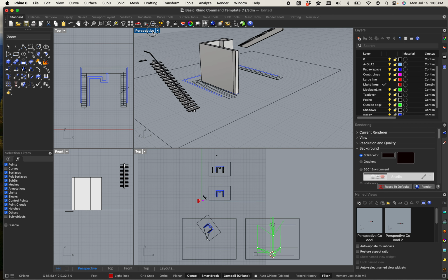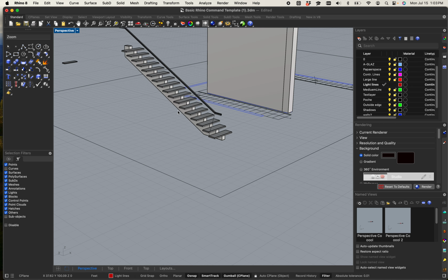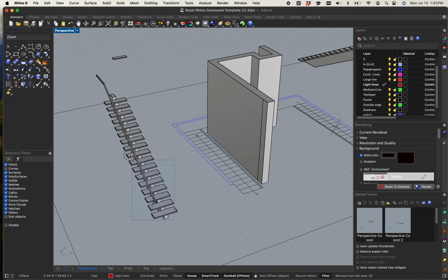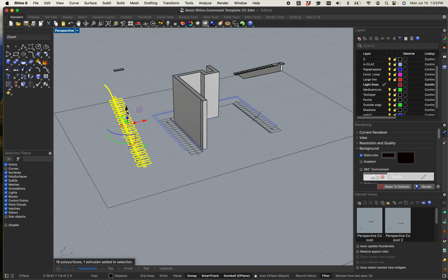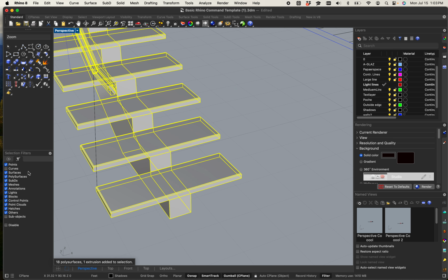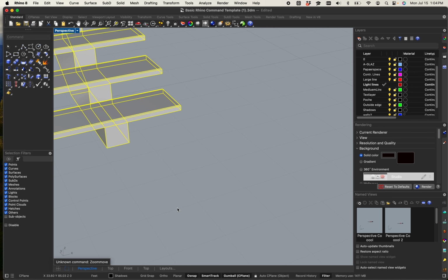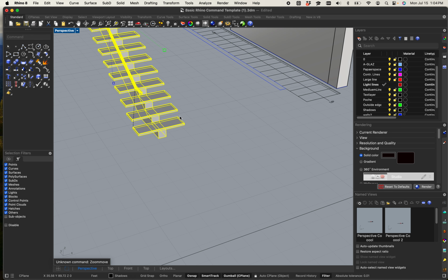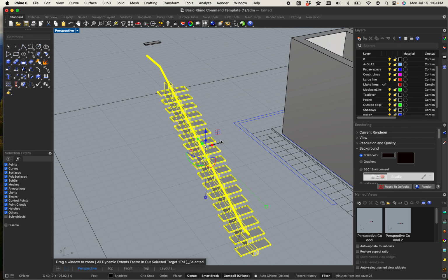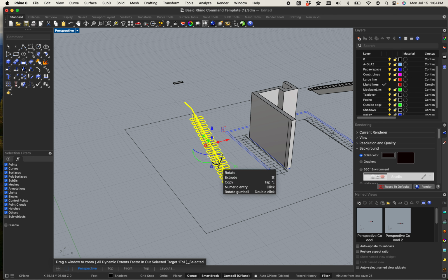So last time we went over kind of 2 different ways to make a stair. I think I ended up with basically kind of this floating stair. Okay. And as you can see, I still have my filter on. I like that it flashes like that, especially on the Mac side, because it really reminds me that it's still on. So let's go ahead and move that and put it in a better position. So I'm going to type in move, enter.